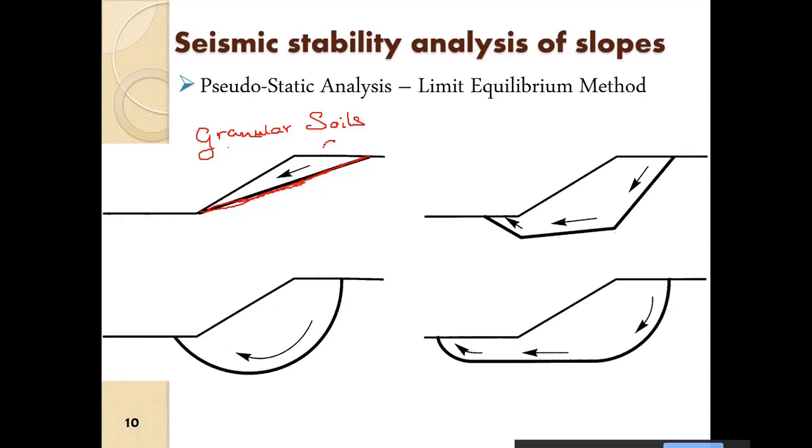So we have the phi value, and C, the cohesion, is approximately 0. It tends to 0. So this is translational motion, where the failure wedge fails in translation. It simply slides out straight, a linear movement. Again, there is a rotational movement, a rotational slump, as we say.